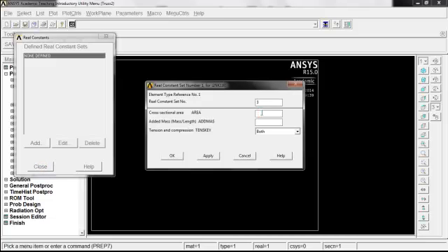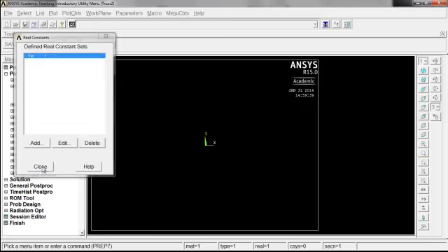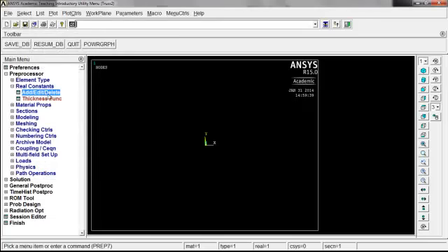All right, we'll have to look at our sheet and see if the sheet indicates that we have a cross-section area of 2 inches squared. Again, remember the units. Right? It doesn't say it anywhere here, but you have to remember in your mind that you have now chosen inches in this particular case. All right, so watch those units. So click on OK there, and we'll close that window.